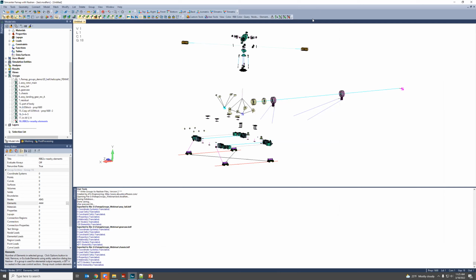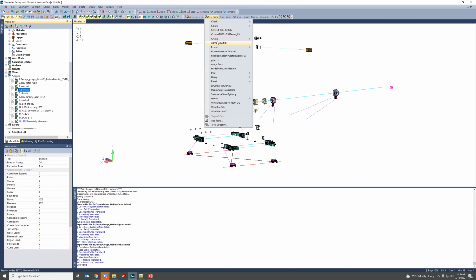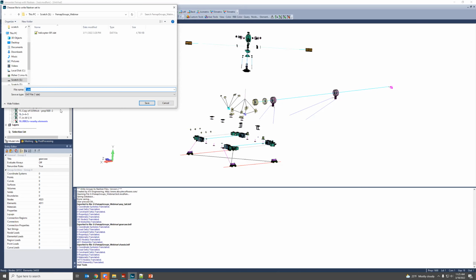The other API I'm going to show is pretty similar. Let's say I want to use those groups as Nastran sets. Now I want to get force on this group. I want to get stress from subcase 1 here and stress from subcase 2 for this group. It can be a bit of a burden to export all of those as different sets with Femap. So we've written this API that will export all of those.